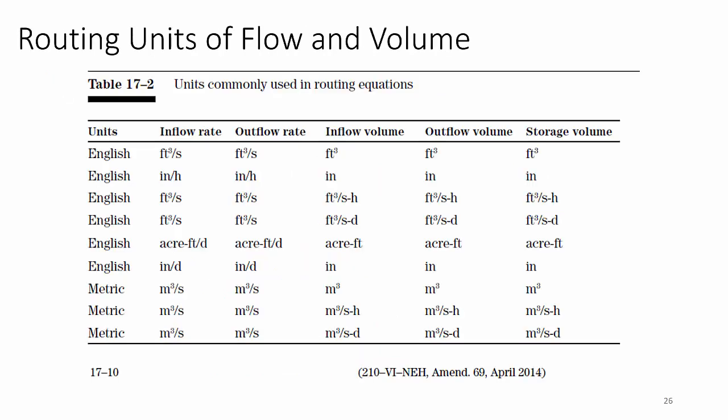Now the units we use here, English and metric units for inflow, outflow rate, inflow volume, outflow volume, and storage volumes are pretty much all over the board, from cubic feet, inches, cubic feet per second hour, cubic feet per second day, because storage volume is a double rate function. It's L^3 over T^2. It's also measured in terms of acre-feet, and then in inches, times the area.